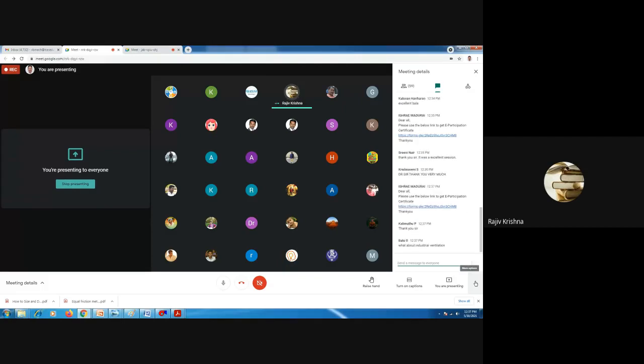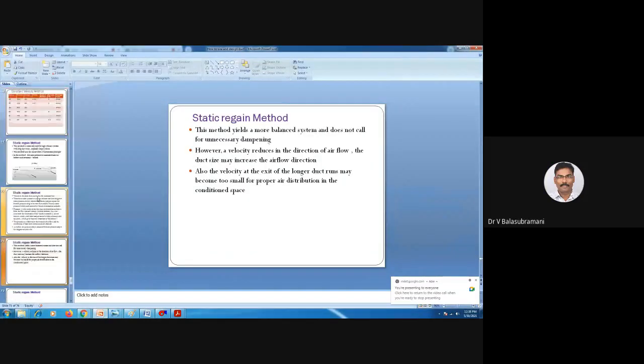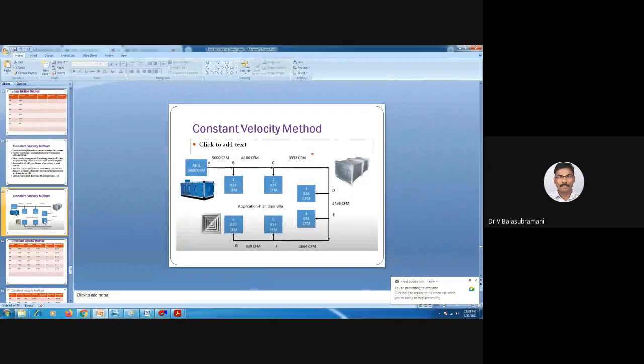Right, sir, in the second method that you have explained, the equal velocity method... sorry, the constant velocity method, you have assumed the value of 834 in the calculation. Actually, what I am doing, sir, is that based on the number of locations, the 5,000 is divided by 6. In my calculator, it gives 833. Here, I can't distribute evenly for 6 locations because of the value.